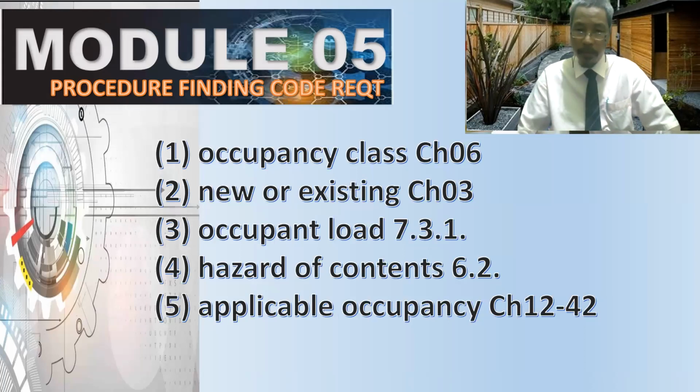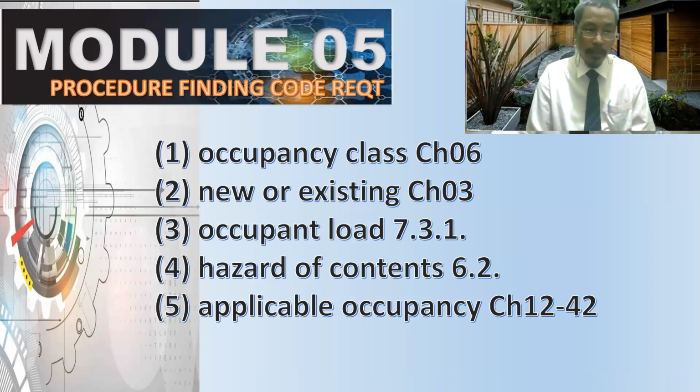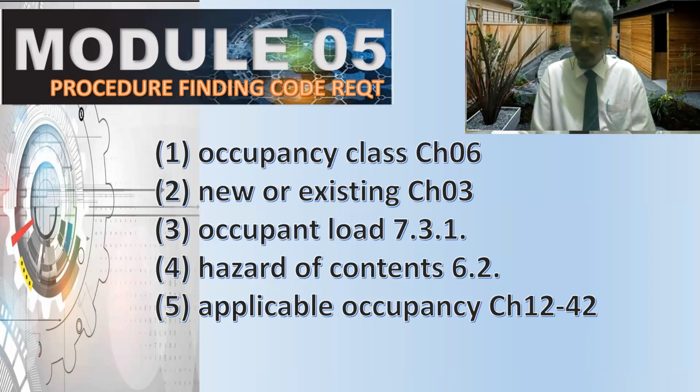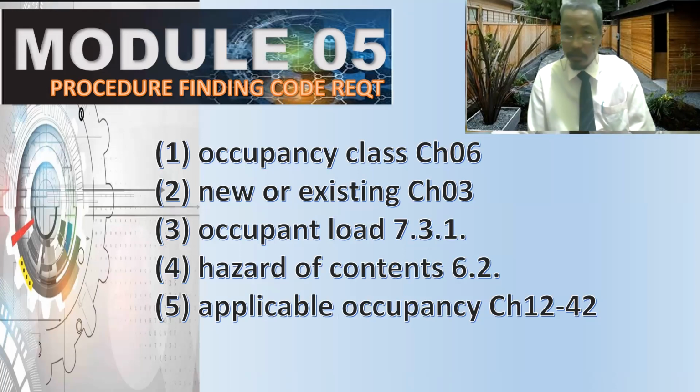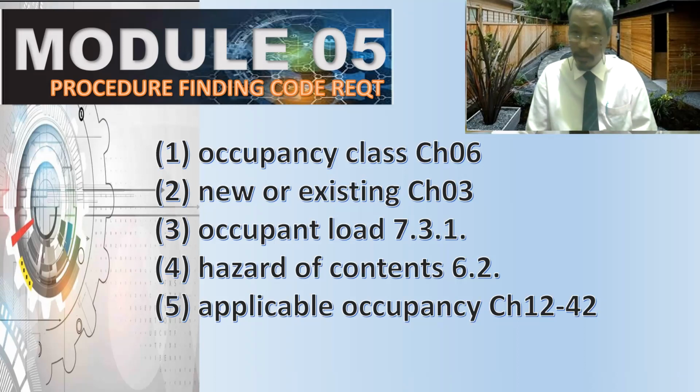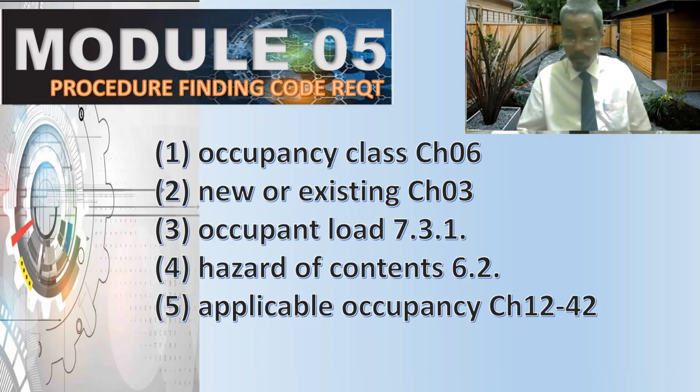The first 5 major steps. First, we have to look into chapter 6, wherein we can determine the occupancy class of our space. Our space could be new or existing, which means we have to look for what? Chapter 3, to be able to determine the definition of new and existing, because there are other conditions.